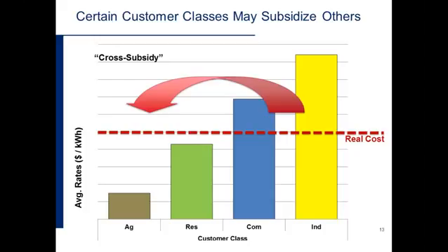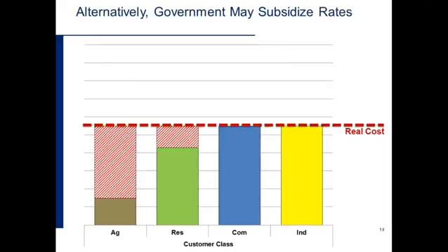So now again, this is a simplified example, and in practice we see cross-subsidization across rate classes happen in many different directions. But in this example, as in real life, the customers with the strongest economic signal to invest in distributed PV are usually the subsidizing rate classes who are paying the highest rates. And when these customers drop off the grid, not only do fixed costs potentially go unrecovered, but on top of that, this cross-subsidy is lost, which further places burden on customers that don't have distributed PV systems. All right, so let's head to the next slide.